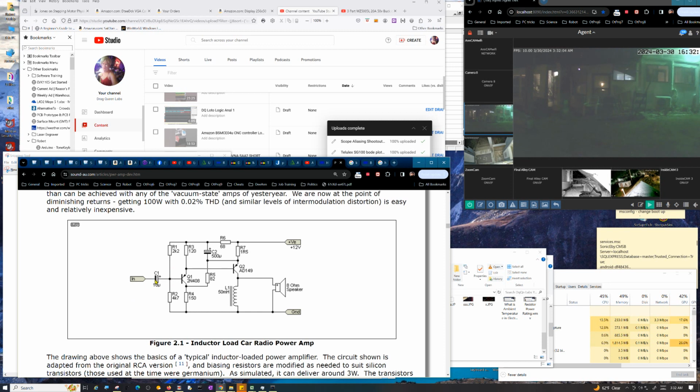That's why you put these in here, so you get rid of the DC part, and it's only the signal that's fed through to your amplifier, assuming your capacitor is fully charged, which usually takes a little while when you first apply power to a circuit. You'll see that on Falstad and some of those simulators. If you do simulations of things like this, you'll see that it may take several minutes of running the simulator before that capacitor actually gets up to its proper voltage. But the fact of the matter is, as long as you've got a DC signal, it's fine.